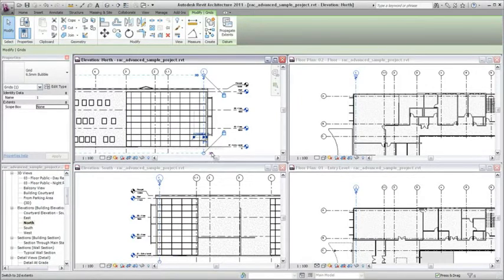Select a grid line and click the 3D/2D setting for the grid. With the grid now set as a 2D element, changes made to it will be reflected in the current view only. The 3D extents of the grid are not modified and are represented by a dashed line with a hollow dot. If you switch multiple grids to 2D before making changes, the 2D extents are locked and will move together.